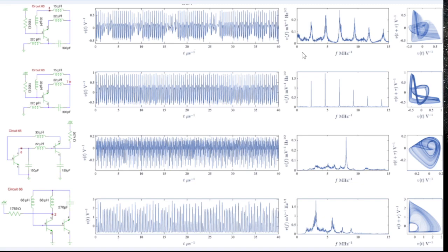And I'm wondering if there's a way to get close to one of these spikes maybe and just kind of listen, you know, change the frequency a little bit back and forth and see if there's something in there. Like you could take a carrier frequency, which is essentially what the receiver does, and then you create. But when you have this frequency that's being generated, and you add the carrier frequency that's being generated, now you've got a sum and difference between two frequencies.